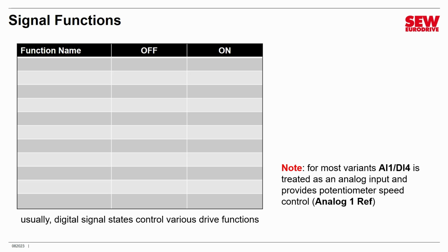All right, let's look at the digital signals and I'll explain what each of them can do. The first is called stop run. With this signal, if the digital signal is off, the motor will stop, and if it's on, the motor will run. That's pretty obvious. Then there is a version very similar to this called fast stop and run. It does exactly the same thing, but the difference is when the signal is off or low, it does a fast stop of the motor using the ramp in parameter 24. When it's on, it runs the motor.